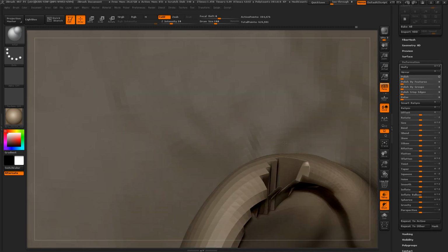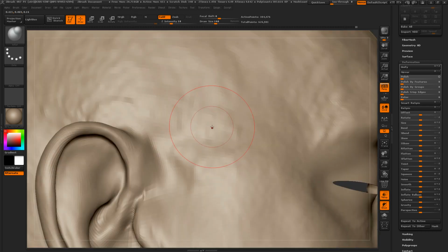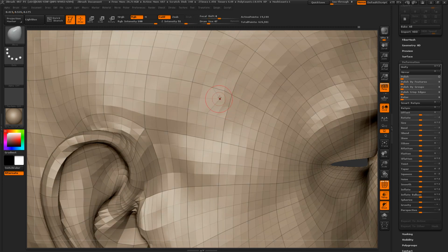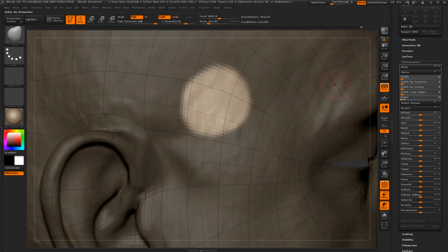Well, apparently it doesn't want to right now because, well, ZBrush hates me. But you get the general idea, I think. Essentially, if you have a bunch of polygons that retain a nice shape, but they're kind of offset like this, and smoothing wouldn't help, and you get some weird artifacts like this that are hard to cover up from multiple subdivision levels, you can usually select an area like that and then relax it, and that should fix a lot of the issues.